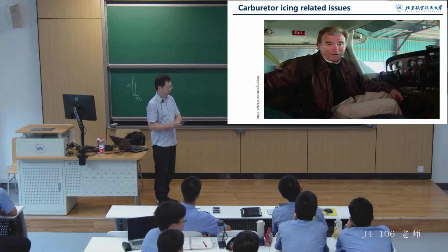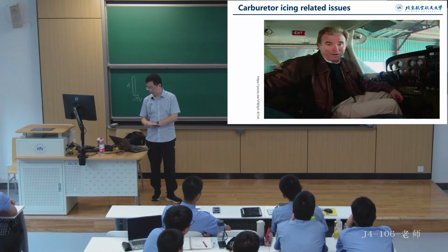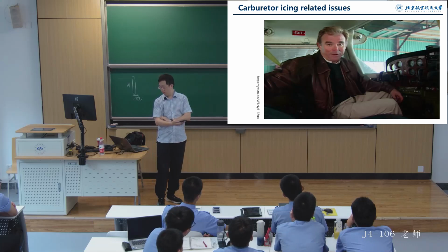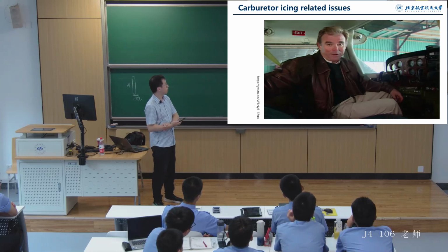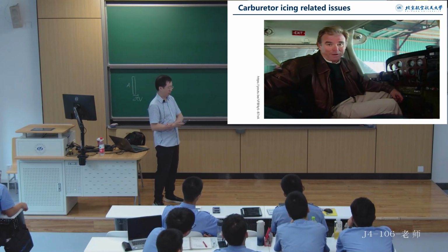A check of a pilot's operating handbook will list the recommended time to apply carburetor heat for your particular aircraft. Anticipate and check for carburetor icing by applying carb heat periodically as an anti-icer rather than a de-icer. And finally, be aware that the use of motor vehicle gasoline or MOGAS can dramatically increase the temperature range for the occurrence of carburetor icing.